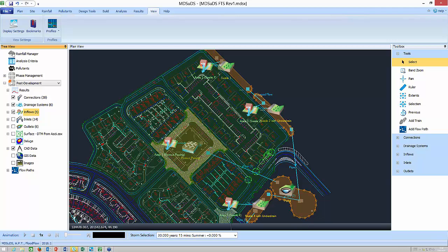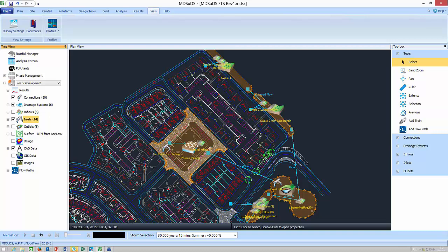How does that runoff get into the structure? If I turn off the areas, there are inlets. So you can see the inlets have been switched on, whether they're lateral flows or point inflow coming in from the car park with the perforated pipe. We have a volume available beneath the permeable paving, and then there's a pipe coming across, and there's a point inflow coming into the pond from the car park.